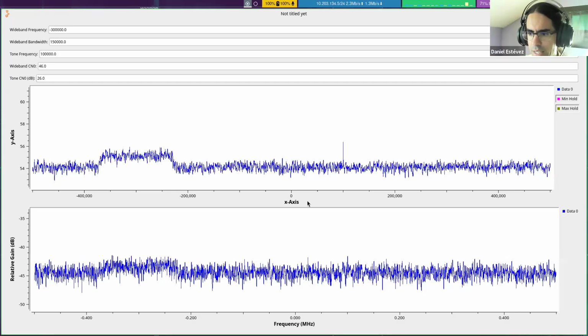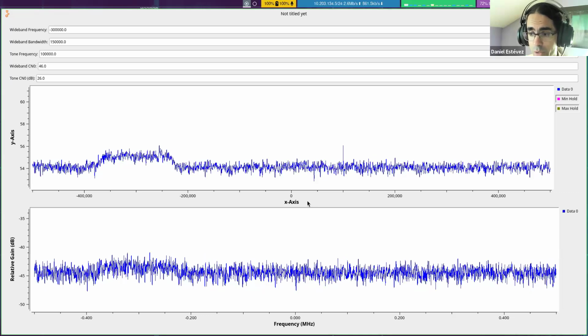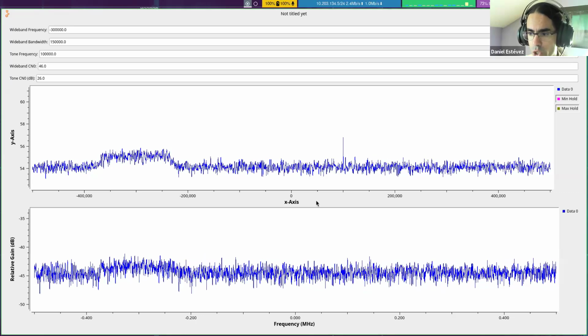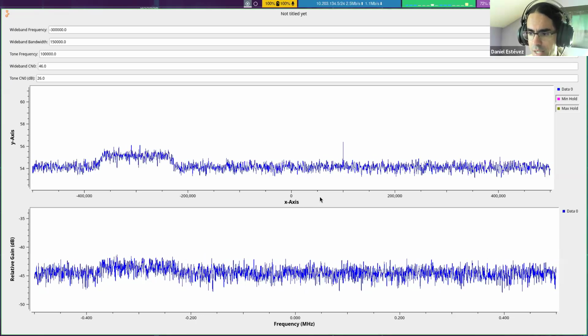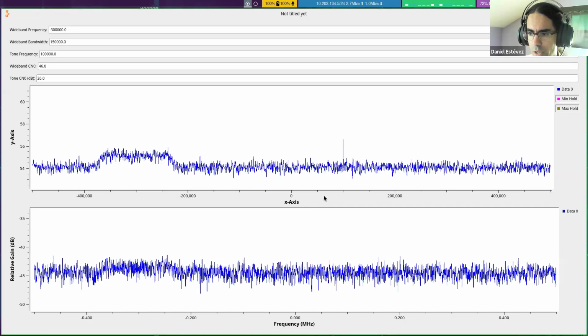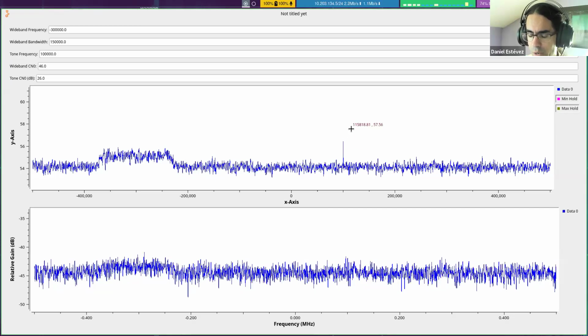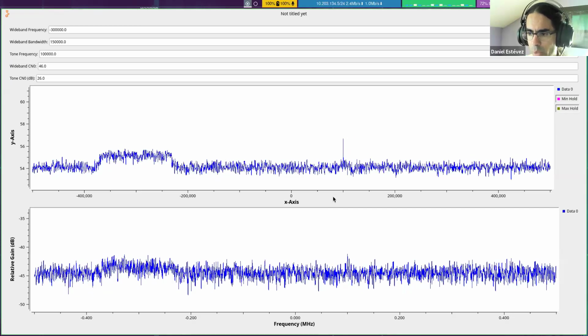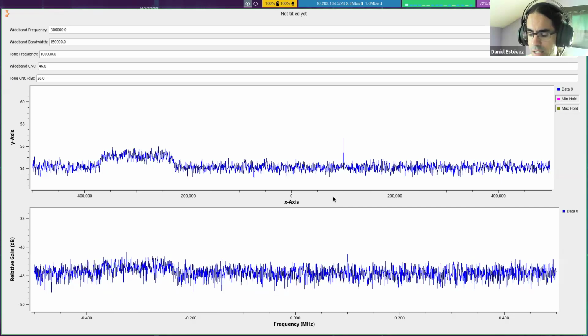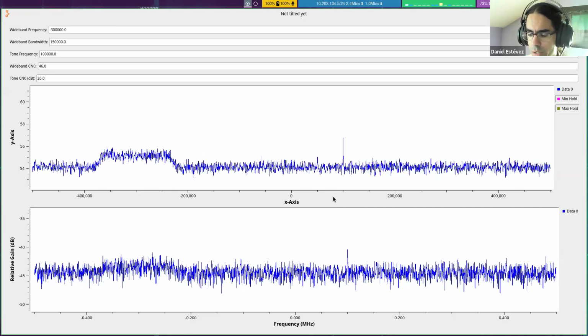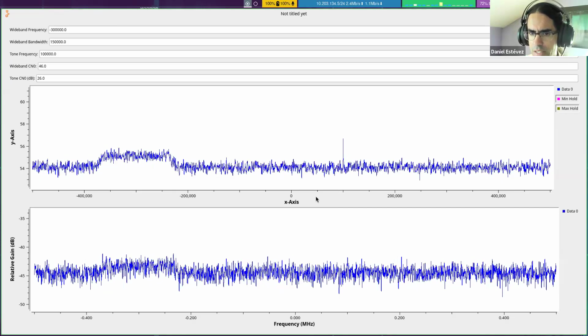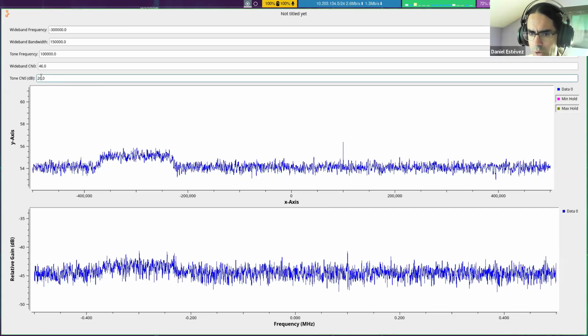Okay, so the next thing I'm going to show, related to what Steve was mentioning, is how the FFT size that we use influences our detection capabilities, especially for this narrowband signal. We have been using 4096, and a question you can ask yourself is why these values?